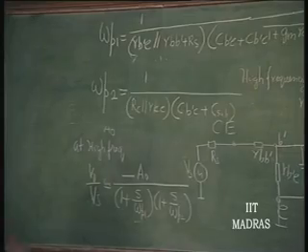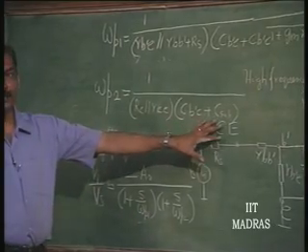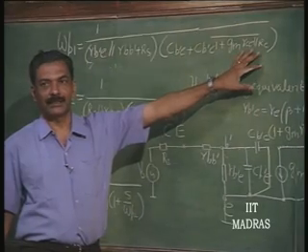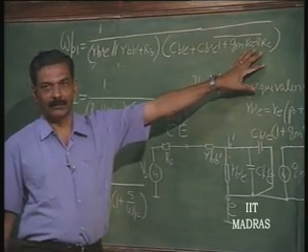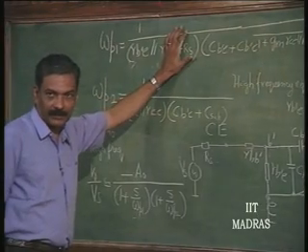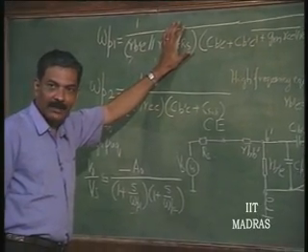So, you can see that this capacitance is very small compared to this capacitance, which depends upon the gain of the structure, which is likely to be high, and therefore, this time constant normally dominates, and that is the bandwidth. How to improve the bandwidth then?